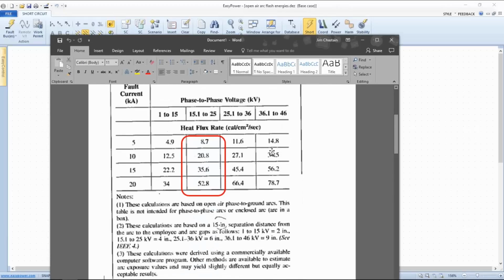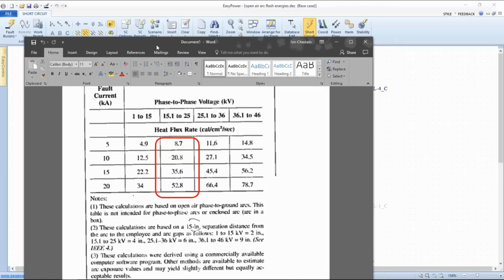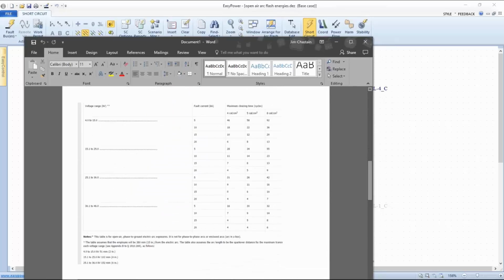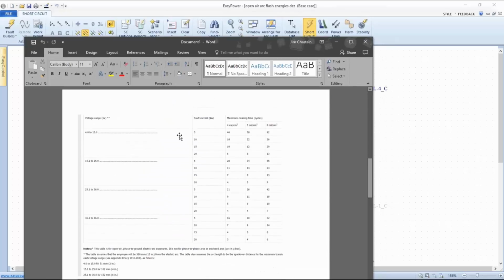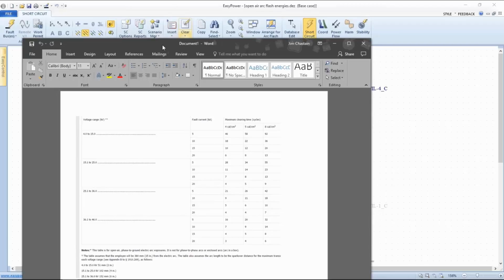But it shows how we've literally come up with adjustments to the software that match exactly these matrix points, and that's what's used as we're applying that model along with the trip times in the tool to produce the incident energy, and they come very close to matching the same numbers that OSHA came up with in these tables that we were talking about.